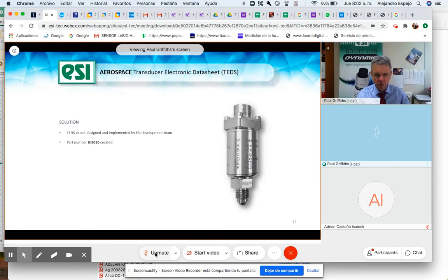So they use their own high accuracy calibration equipment and systems, and they made their own calibration records. They wanted our calibration records, but they would work to their own. So they loaded the transmitters with data from their own calibration. So pressurization up and pressurization down, lots of information.